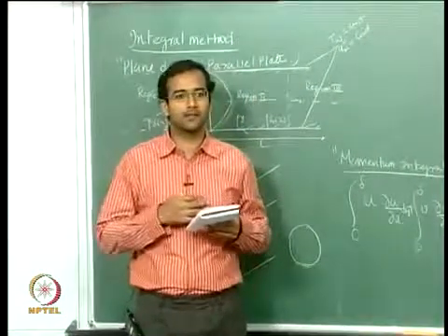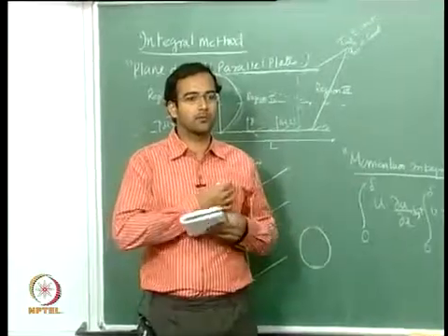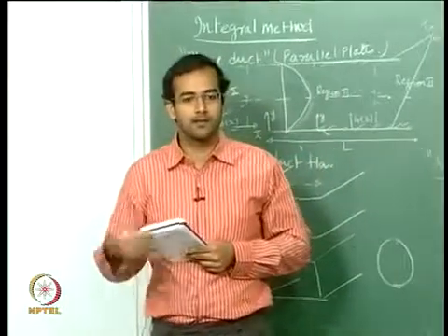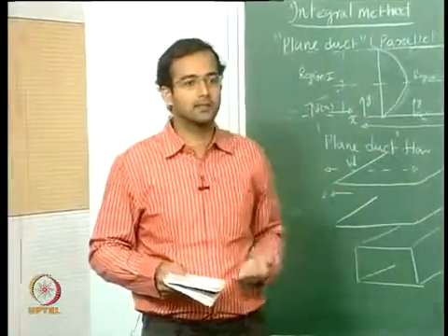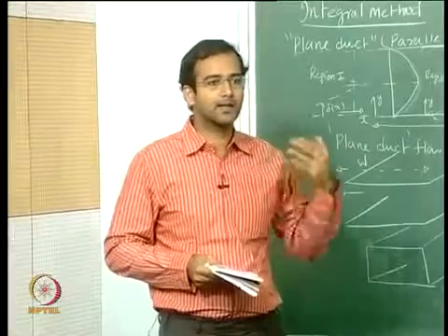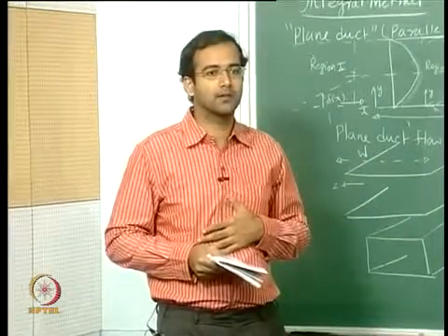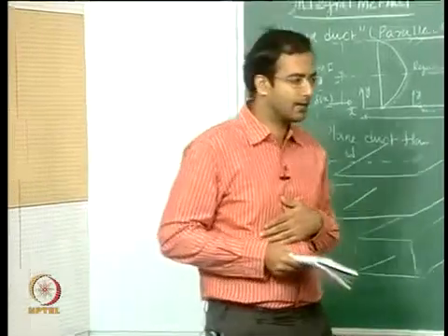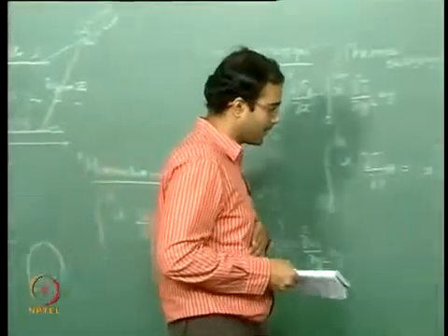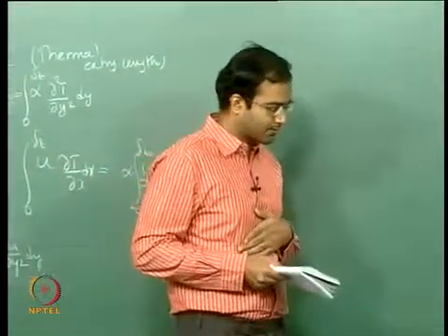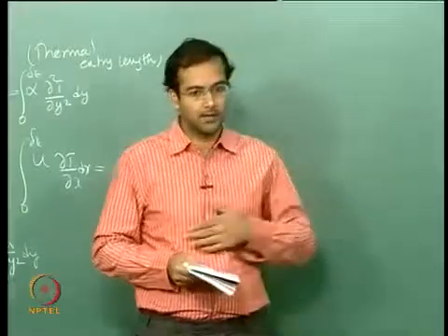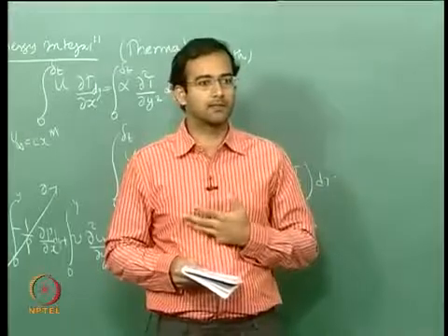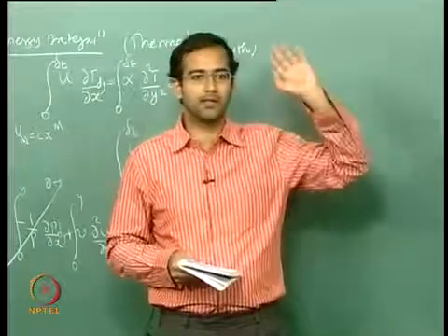It is not as wide as in external flows, where you used it for almost all the problems where you had a similarity solution. You replace that with an approximate solution, and in fact even more than that for cases where you had an unheated starting length, for example. There you cannot use the solution from similarity variables. The cases with a pressure gradient were also much simpler, and also the case where you had a non-uniform wall temperature or wall heat flux, with a linear variation or some other variation, any variation.